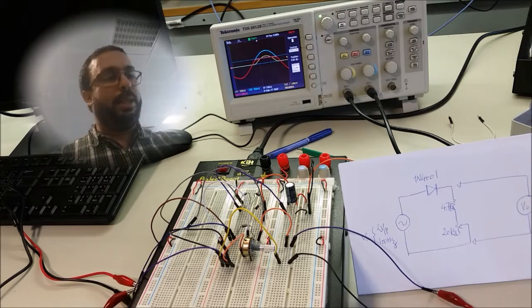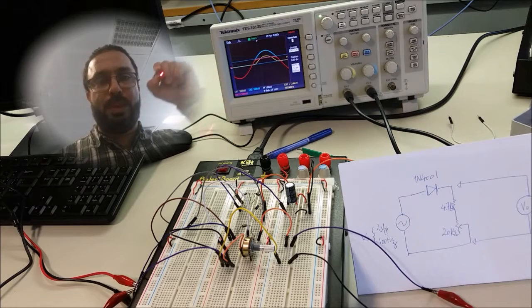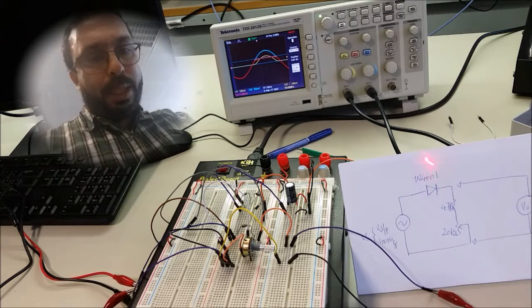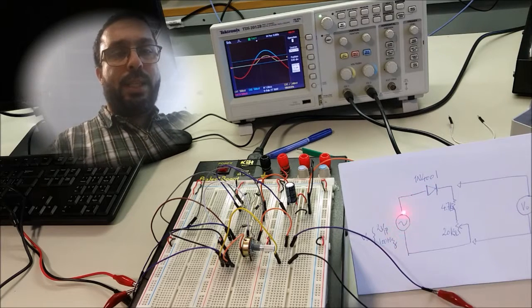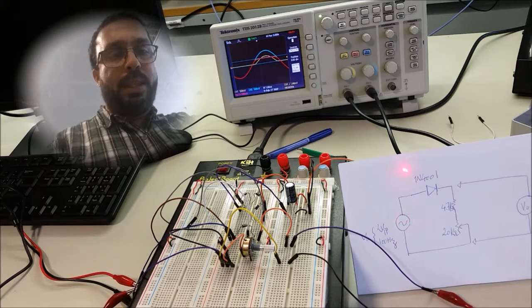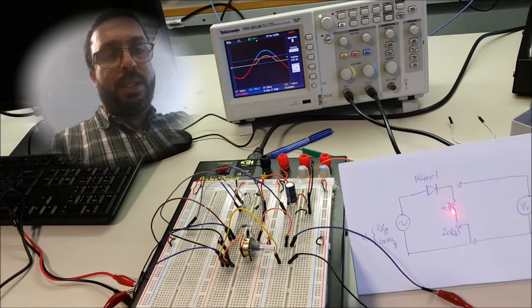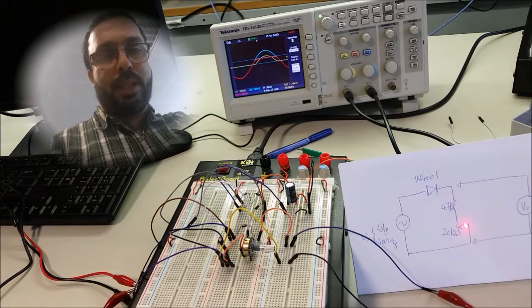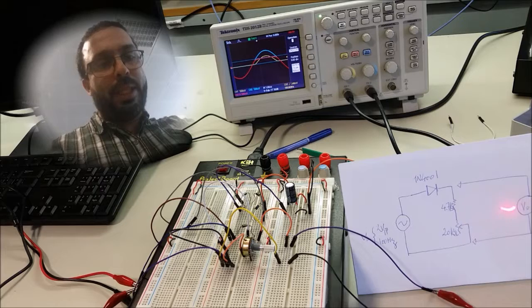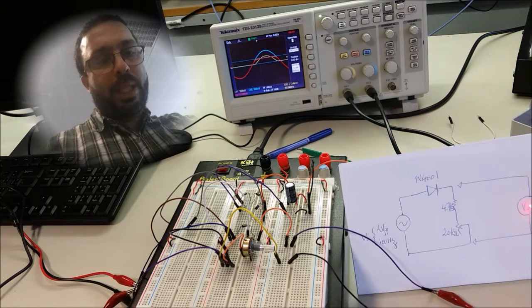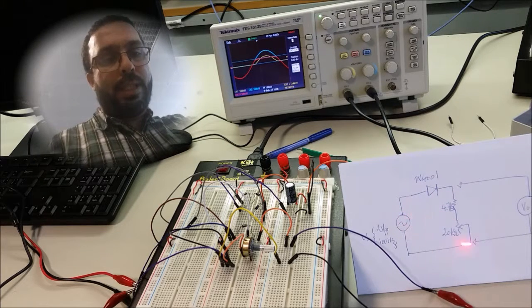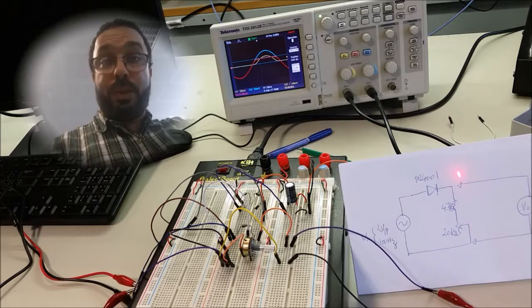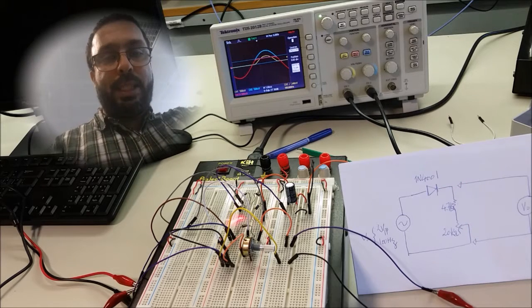I'm going to use this pointer to show you here on the bottom right the circuit for the rectifier. So basically we have an AC signal, followed with a diode in series with a resistance. And this is the circuit we are trying to implement here. We are going to watch how the output voltage, V out, changes with the input voltage. So this is the schematic of the simple half-wave rectifier. And this is the circuit itself.